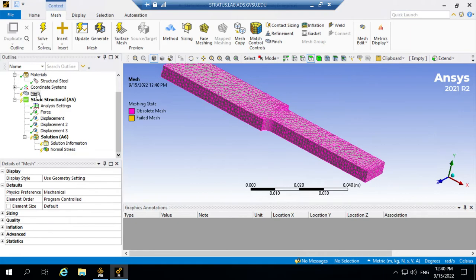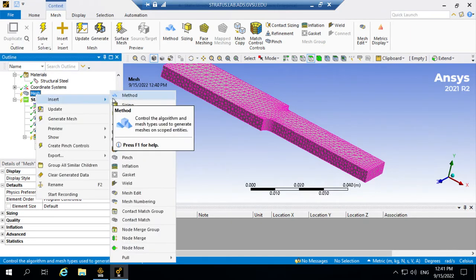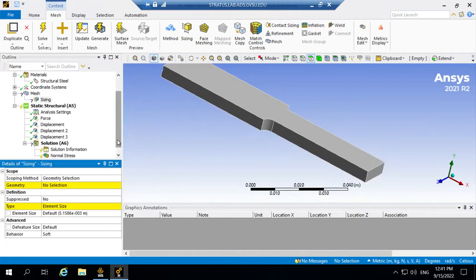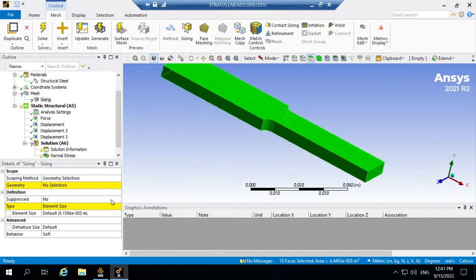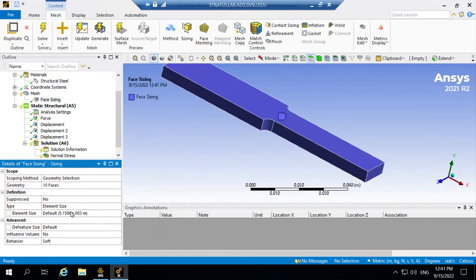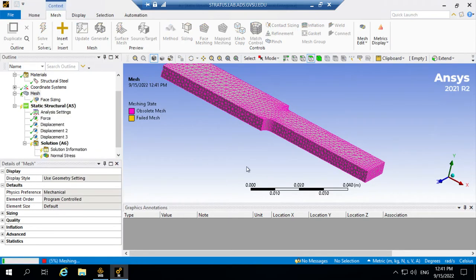Then you can get closer. Your stress concentration is going to be closer to what you see in reference books. Alright, select all, element size, as you saw, I made it 10 times smaller than the default. Let's look at the results now.